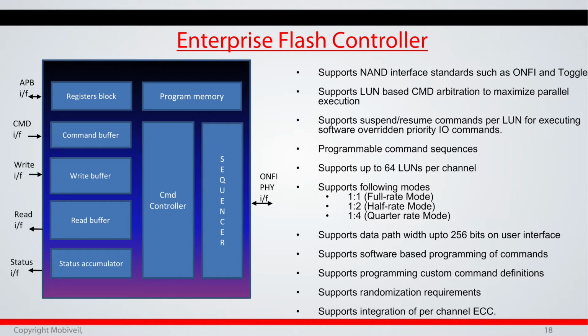But what is also important, or a pretty useful feature in this controller, is that everything is an independent interface. You have a control interface, then separate command, write, read, and the status interface. So there are individual interfaces, pipelined, and you have flexibility to define additional commands in silicon. That is very important for flash, because some of the flash commands only the user will be informed about by the flash vendor, and no one else will know because those are very secret commands.